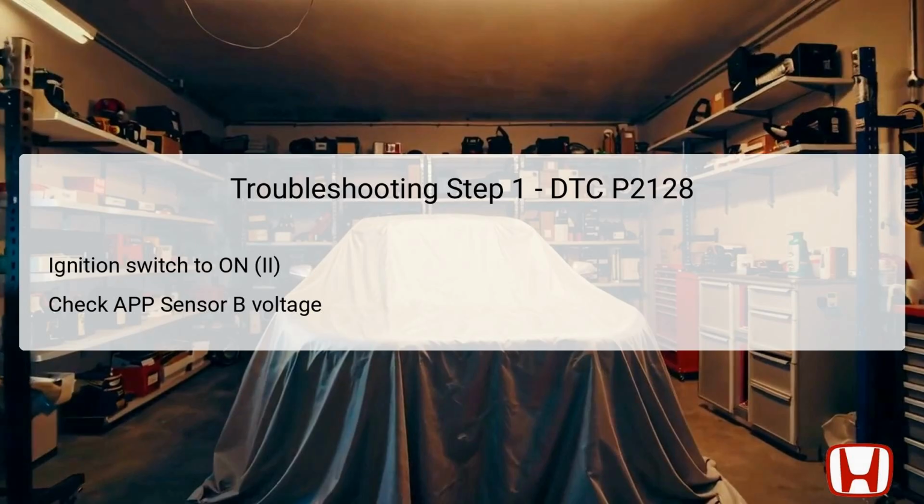If the reading is within this range, it indicates that the sensor is operational at that moment. However, if the reading falls below this threshold, it may indicate an intermittent failure, meaning the system is functioning temporarily. Investigating poor connections or loose terminals at the APP sensor and ECM is essential if the voltage is inadequate.